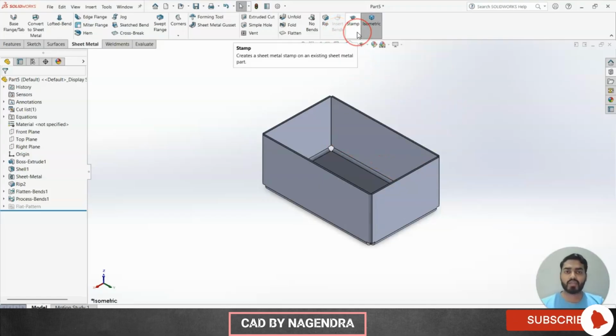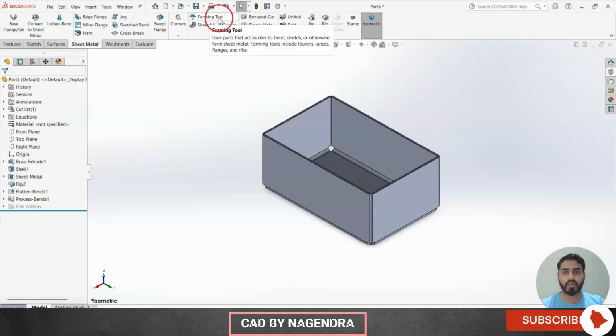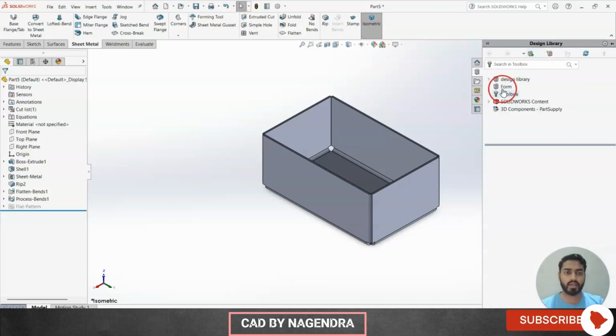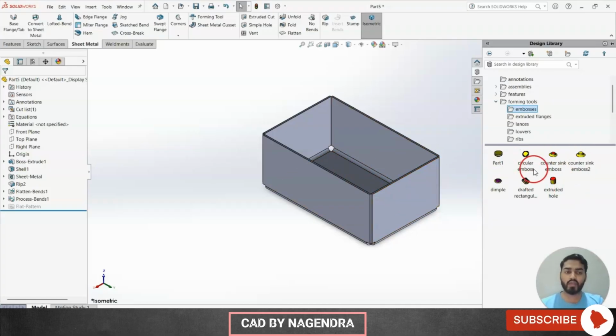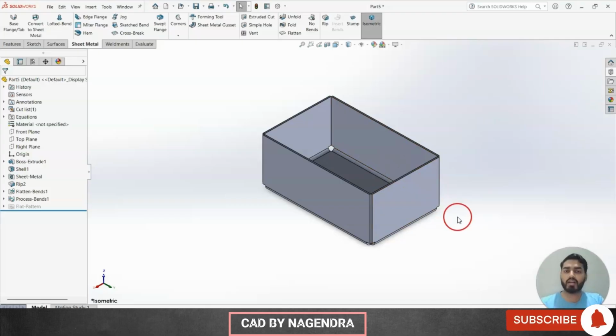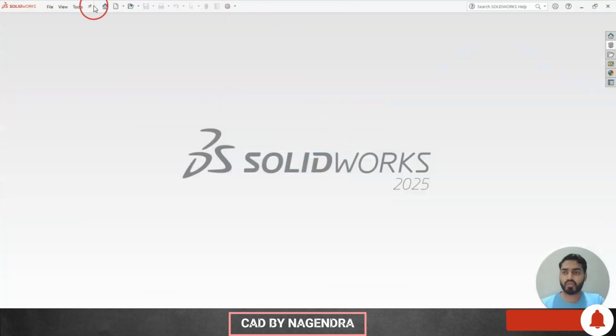Then the last option we are having here is stamp. So stamp is nothing but, already we have seen forming tool. If you go to the design library, under this design library we are having forming tools. Different types we are able to drag and keep here. In the before video we have discussed this, and how to create our own also we have discussed. But if you are using the latest 2025 SolidWorks version, then only you can use this option. In earlier versions this option is not available. So let me show you how to use that.